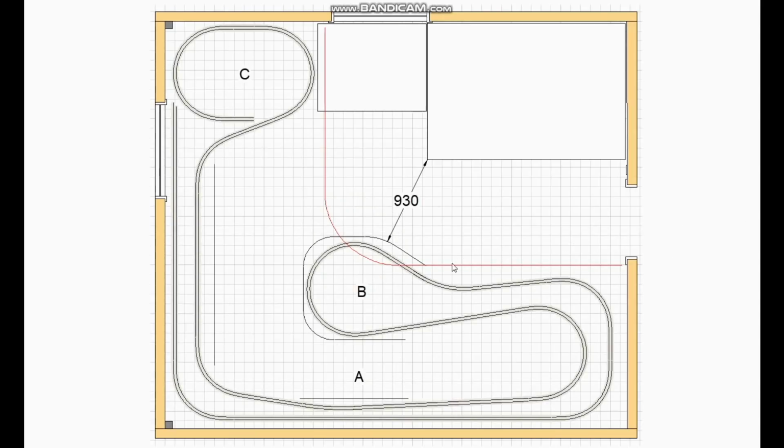Here is one plan that I drew, showing how by shaving the benchwork along one wall down to a bare minimum and accepting a much narrower aisle, in this case only 600 millimeters or around 2 feet, we can just about get a peninsula in. And although it does cross this red line, we still have adequate clearance between the benchwork and the corner of the bed.